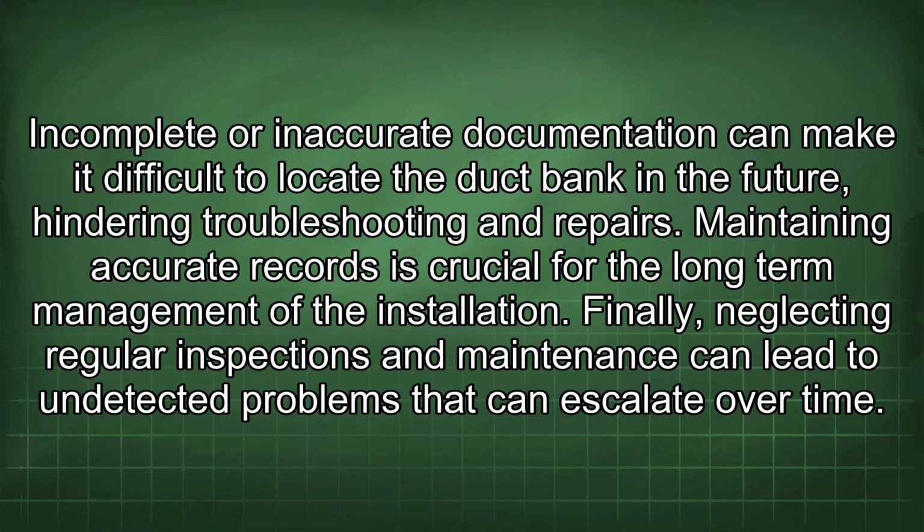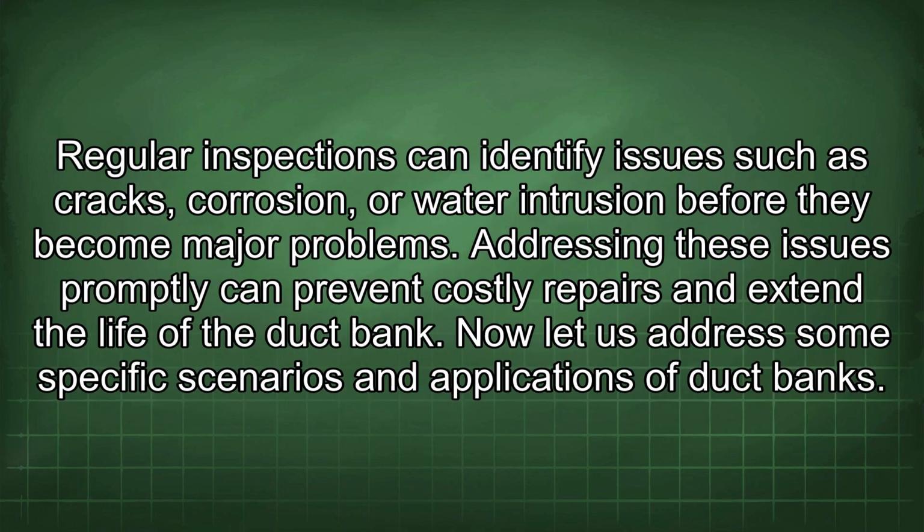Finally, neglecting regular inspections and maintenance can lead to undetected problems that can escalate over time. Regular inspections can identify issues such as cracks, corrosion, or water intrusion before they become major problems. Addressing these issues promptly can prevent costly repairs and extend the life of the duct bank.